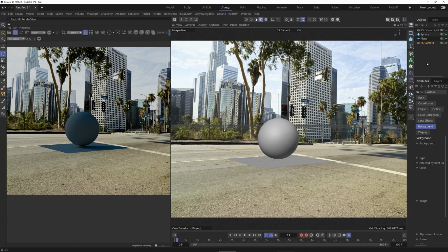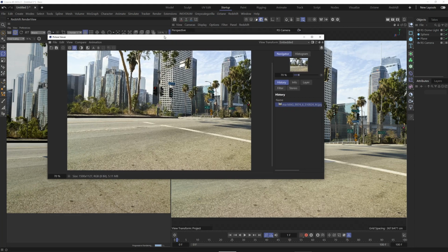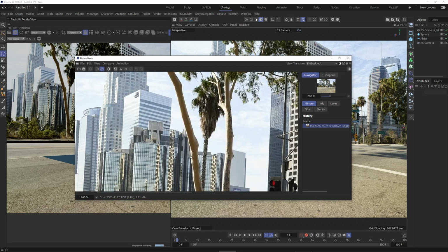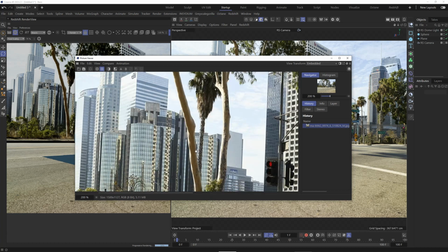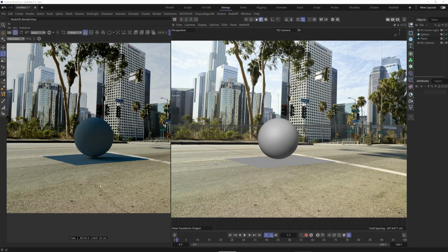Finally, I adjust the HDR a bit. To look at the shadow cast properly, I zoom in closer. This helps us to better assess the situation. The shadow cast becomes clearly visible, especially at the tree where the light hits. You also notice the sharp edge of light there. Additionally, you can see the shadows of the plants. This allows us to adjust the light so that it is parallel.